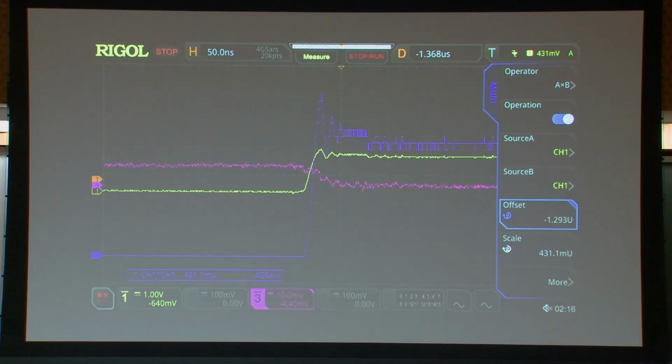On the other hand, whenever you see those ripples, that's because when the switch is on, it acts like a resistor. So it has some RDS(on) and non-zero current, I squared R, which makes the loss. The math shows the multiple of the voltage and the current, and you can observe a triangular shape of that.